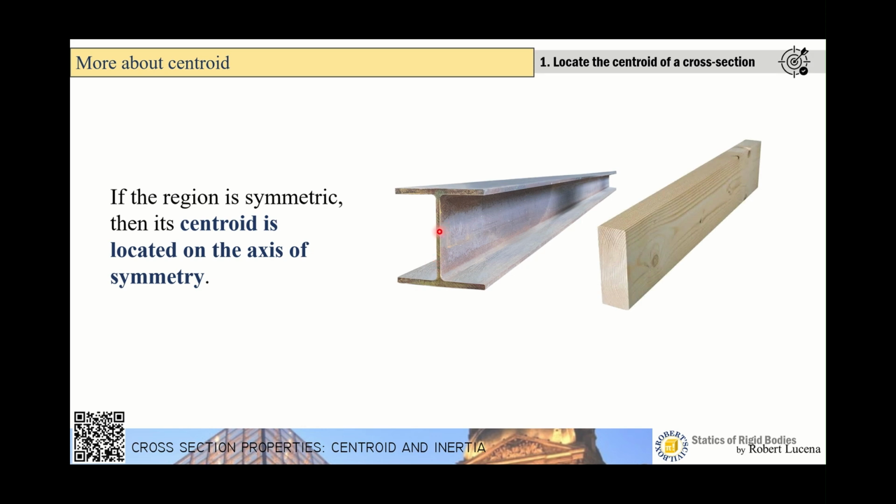So most definitely, for a rectangle, the neutral axis should lie on the mid-height. It's because it will give you equal area on top and the bottom. For a triangle, for example, obviously, the neutral axis should not lie on half of the height of the triangle, basically because the lower portion will have more area than the upper portion.